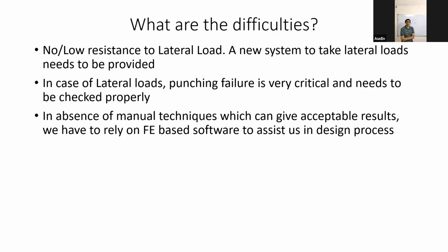If you have heard about the capacity design method, or where yielding takes place in a structural system, generally you will see that in a slab beam column system, the plastic hinges, or what we call the mechanism, take place in the beams. Your mechanisms or plastic hinges form at the beam locations in case of your slab beam column system.